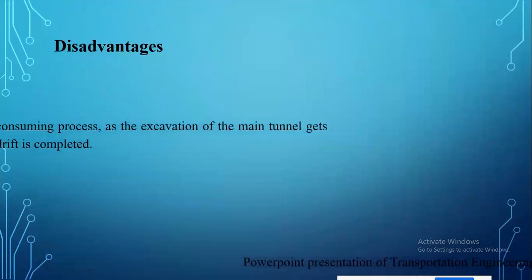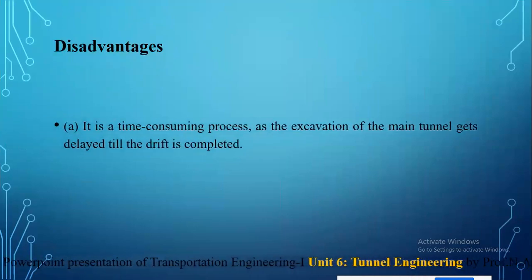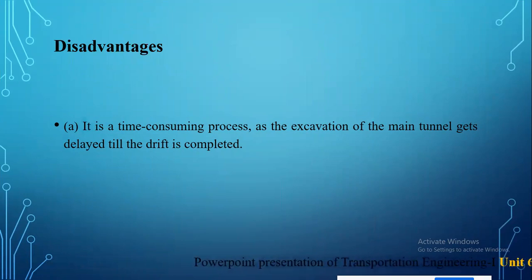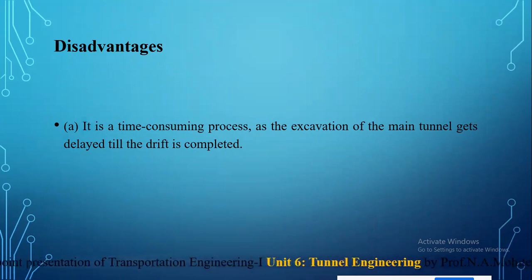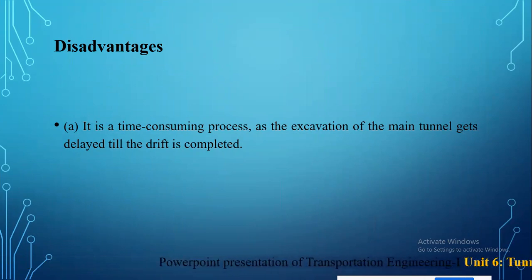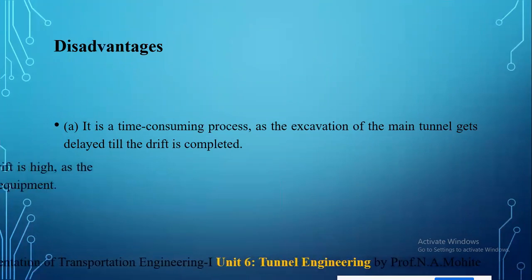So what are the disadvantages? It is a time-consuming process, as the excavation of the main tunnel gets delayed till the drift is completed. We have seen that it can be from the top, from the bottom, from the side, or from the center. The main tunnel which is required, that task is only remaining, resulting in a delay in the correspondingly completion of the said tunnel excavation.